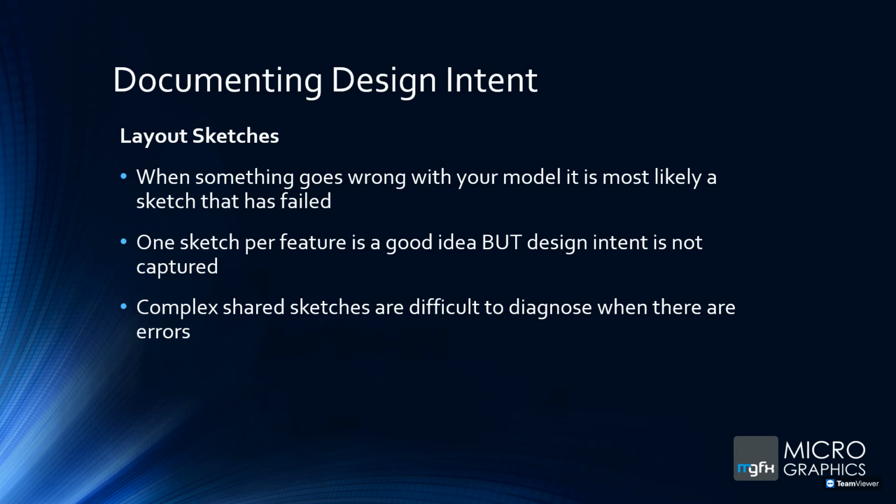Layout sketches. So this is actually a nice way to control your model as well. Your layout sketches create a sketch that lays out exactly where everything's going to go. And as I said, if anything's going to go wrong in your model, it's most likely the sketch. When we started working in Inventor, we were taught one sketch per feature.